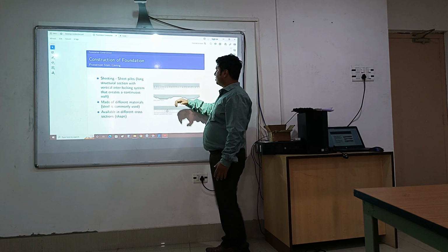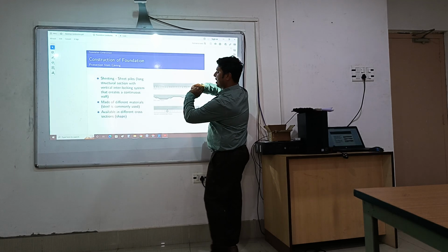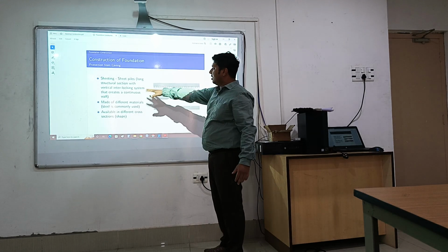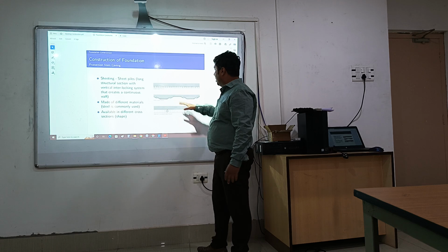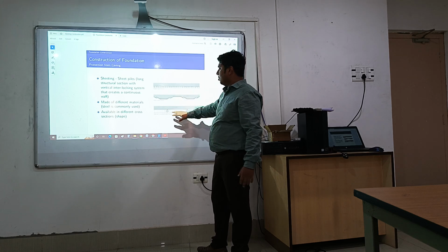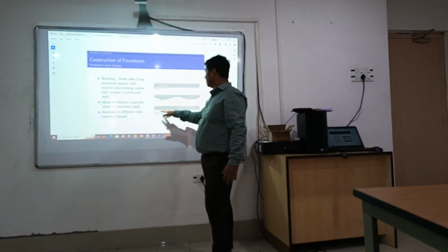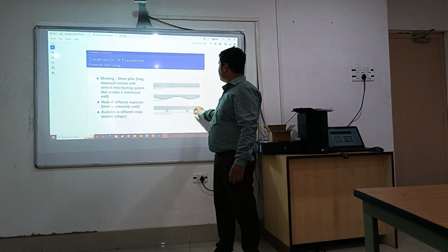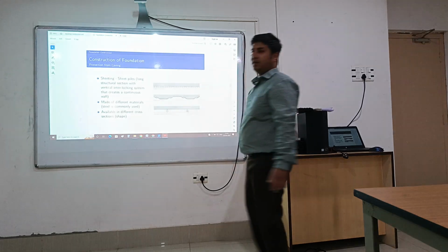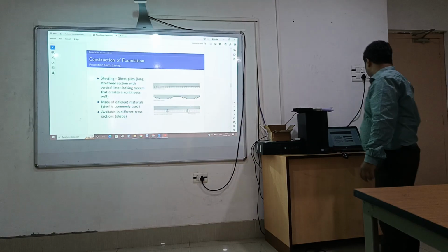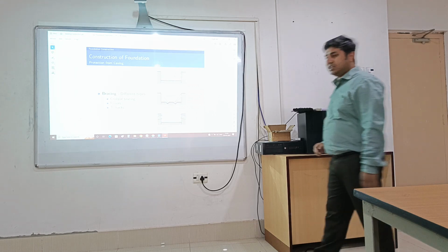Also, there are some sheets like these blocks. They are attached by interlocking, and in this way we can create a continuous barrier for the material to stay. We can also use cross-shaped sections which are attached. They are put in and then locked using locks. So by this way, sheeting can be used for protection from caving. We can use dressings also.